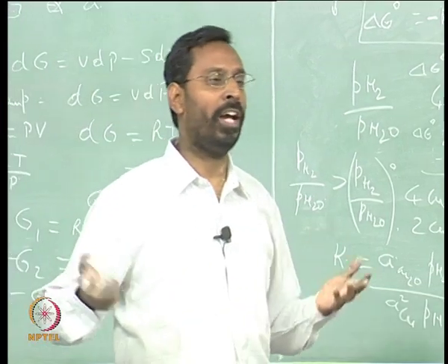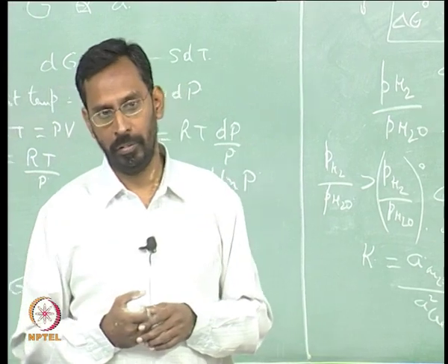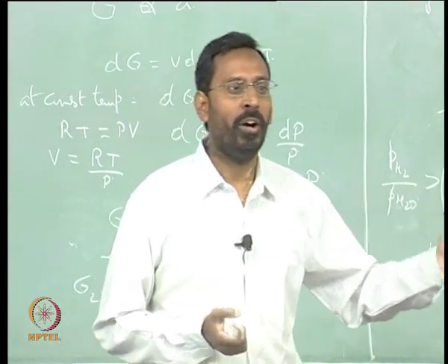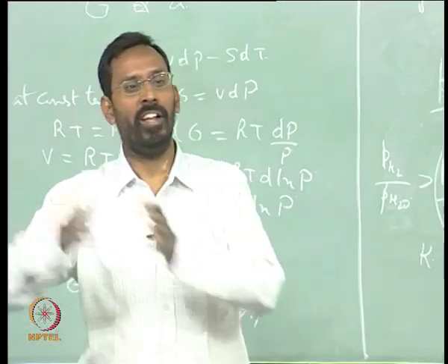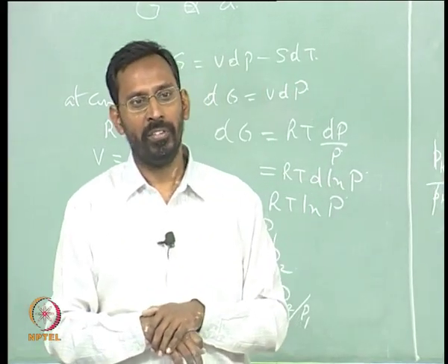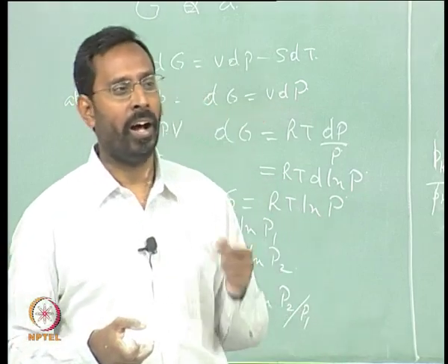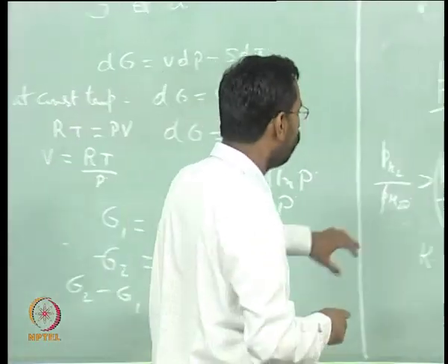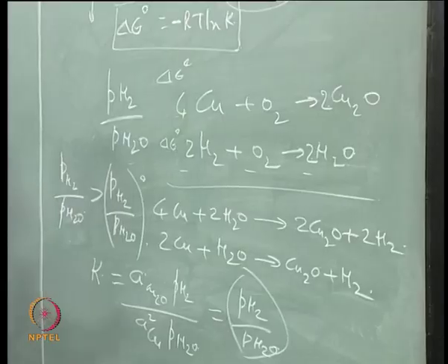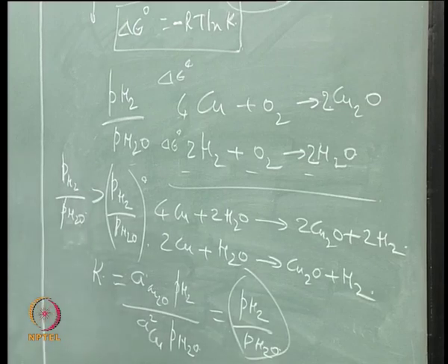But if I have alloying elements of the order of 20-30%, then ideal solution may not work out. So, that is where you have to consider that activity is activity coefficient times the mole fraction. So, all these complications will come into the picture when you are talking about materials where you do not have pure components. As long as pure components are there, these equations turn out to be very easy.